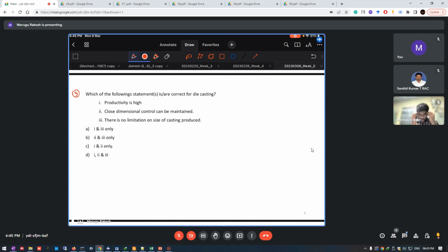Okay, so let me discuss. Which of the following statements is correct regarding die casting? First, productivity is high in die casting. That is true. Close dimension control can be maintained. That is also true. There is no limitation on size of the casting.